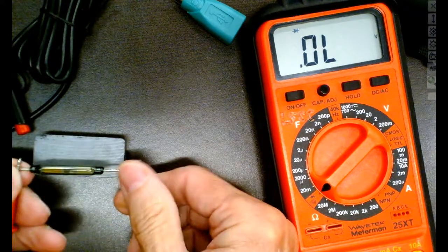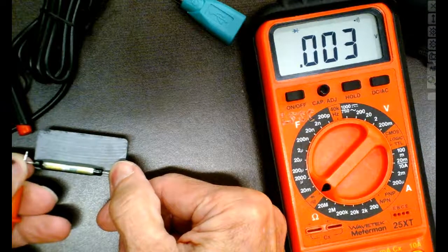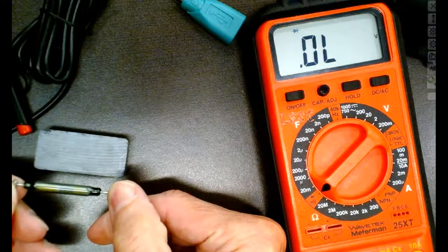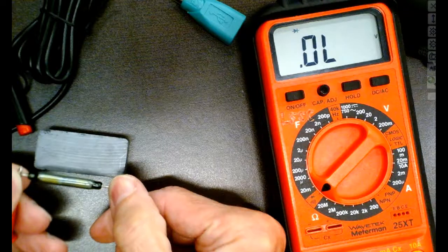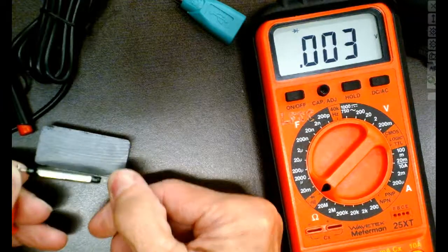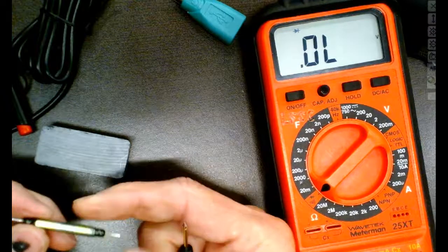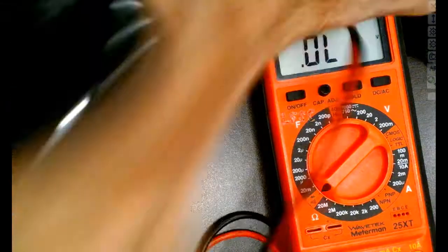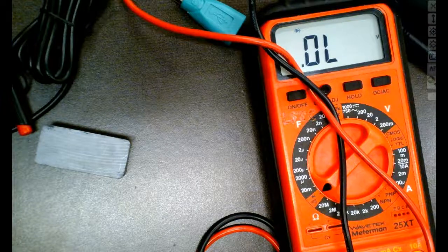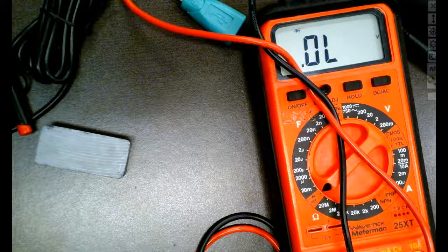I can't hold it. I don't hear it. So when it comes close to the magnet, the switch does what? Closes. When I get away from the magnet, the switch does what? Opens. So we use this one here to sense a magnetic field. It's not solid state, so we do have a mechanical mechanism in here that could go bad, right? Anytime we have electromechanical devices, we have two things that can fail.